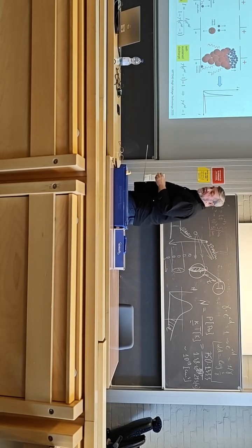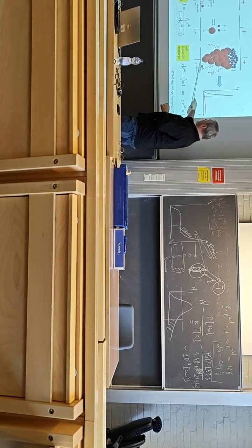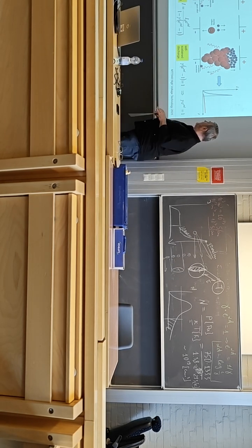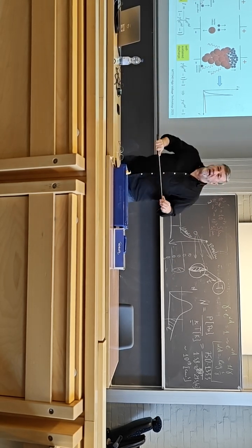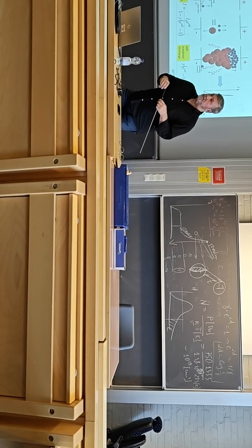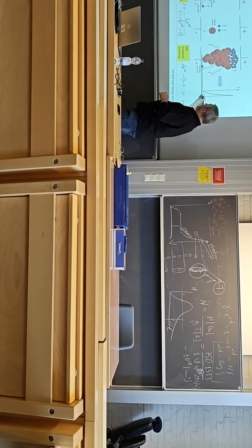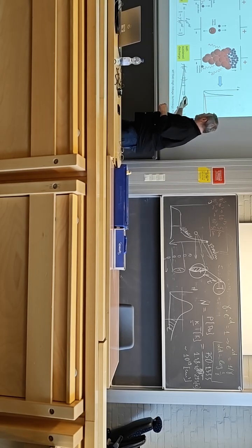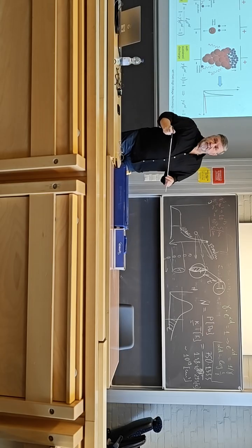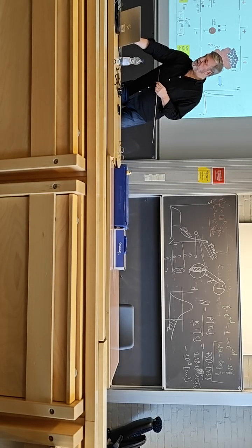So this Townsend breakdown, the Townsend mechanism, is supported by the secondary processes on the cathode. And this is different from another mechanism which we'll talk about later, which is called streamer breakdown. So Townsend breakdown is supported by secondary processes. This gamma is about the yield of secondary electrons from the cathode surface. Okay, questions?